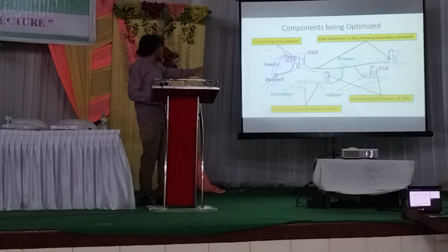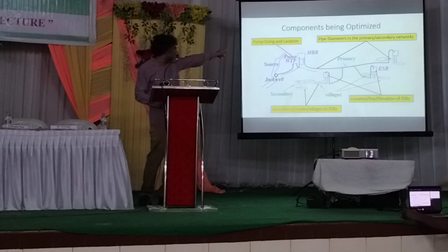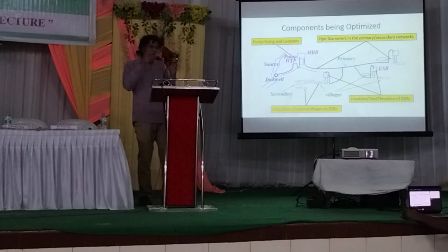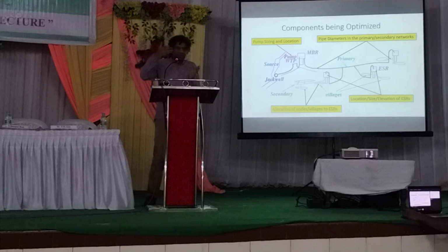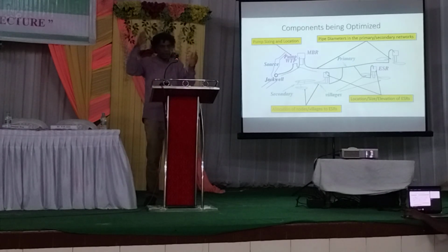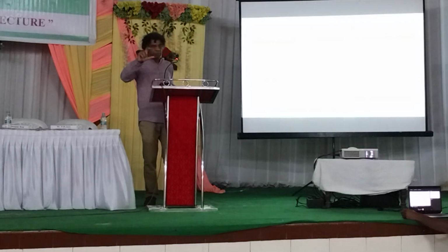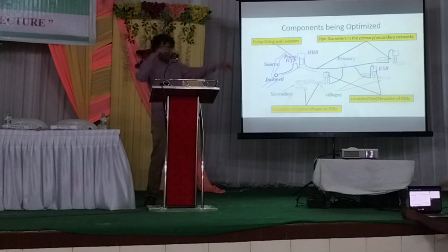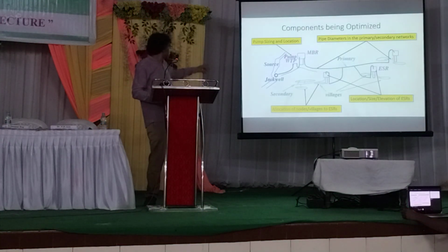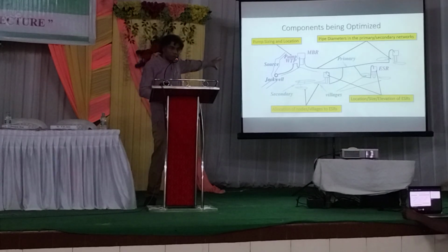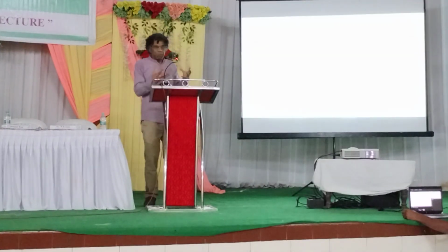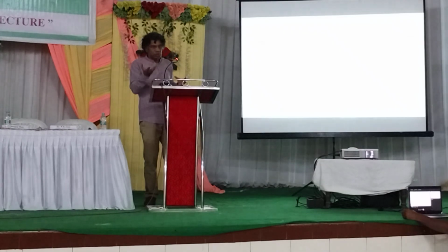So what is the water network design problem? Like I said, first is the pipe diameter. What pipe do you use? Usually pipes come in discrete sizes. So there is a set of 4 or 6 or 10 types of pipe. You say for each link in the network, I have to use one of the pipes. And usually those are identified by their diameter. Pump size, how big should the pump be? Because there is energy cost associated with the pump.